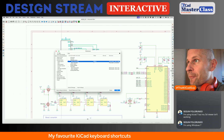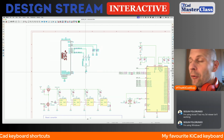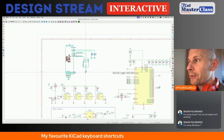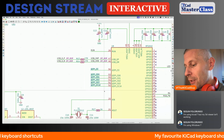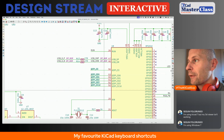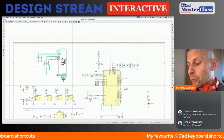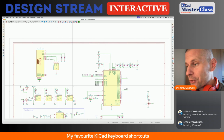So the first one is horizontal mirroring. How it works: select the block or a symbol and press Shift X, or X in your case. You mirror the entire block. It can be a block of labels, it can be anything. I use it frequently when I want to refactor the schematic. So this is X-axis mirroring, or horizontal mirroring.